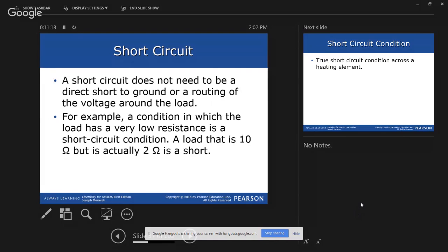What I was talking about with the short is I've seen lots of motors, when they start to fail, you'll start tripping one overload. You measure the resistance off each coil and see if there's a noticeable difference. You can even check a shorted winding with current. Just take an amp clamp, and the one that's shorted will draw a lot more, and you'll definitely see an imbalance. Once you start seeing an imbalance, it's too big of a deal. You might as well just get rid of it.